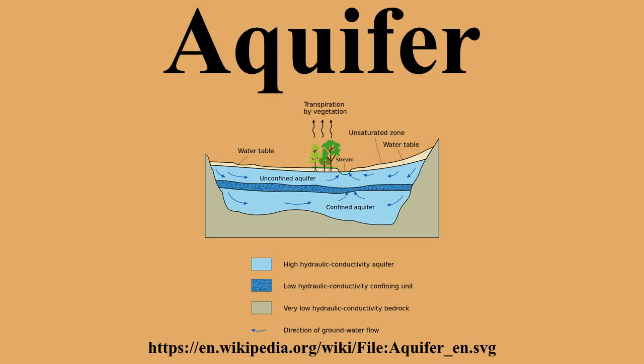Saturated means the pressure head of the water is greater than atmospheric pressure. The definition of the water table is the surface where the pressure head is equal to atmospheric pressure. Unsaturated conditions occur above the water table, where the pressure head is negative and the water that incompletely fills the pores of the aquifer material is under suction. The water content in the unsaturated zone is held in place by surface adhesive forces and it rises above the water table by capillary action too.